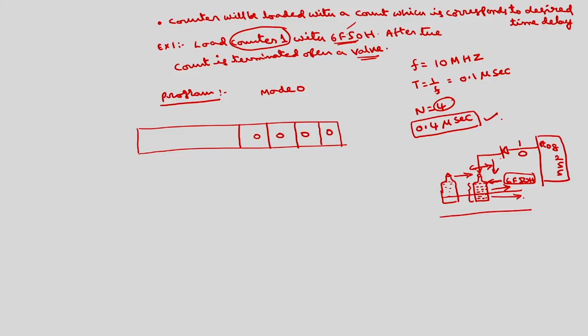Okay. So these 2 bits will decide RL1, RL0. 1 1 is the total 16 bit count. First it will take the lower order 8 bits, then the higher order 8 bits. Here, because our count is 16 bit, you have to load 1 1, so that it will first take the lower order 8 bits and then the higher order 8 bits of the count.